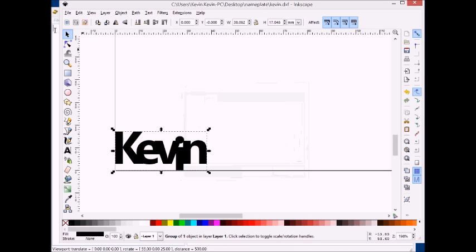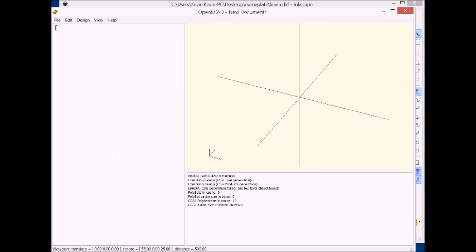Okay, now go into OpenSCAD. The first thing we have to do is, it only finds these files in the directory where the SCAD document is, and we don't have a saved SCAD document. So we can type our SCAD document, but it won't do anything. Import, we could say, I'm sorry, linear extrude. And then we say height equals 2 millimeters is a good one for a quick print.